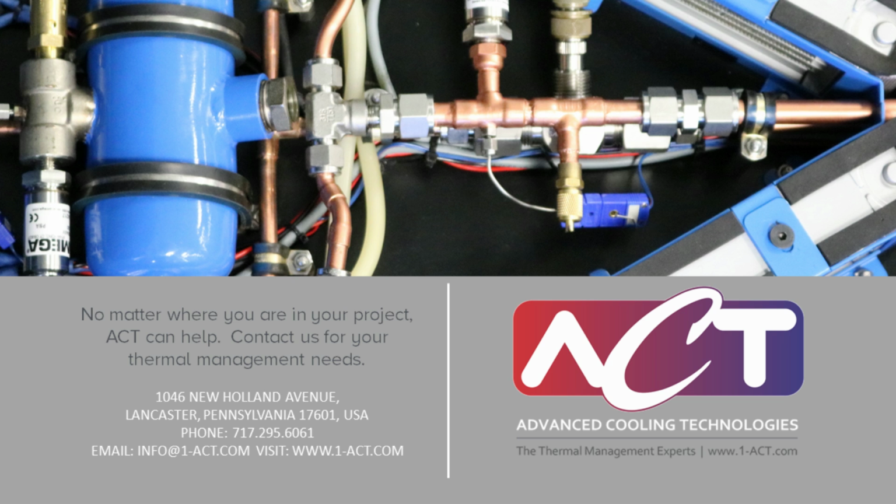to give you something very robust and reliable. So the typical testing might be a couple of thermal performance checks throughout the process, maybe some pressure checks, to make sure that you're able to hold back the vapor pressure of the ammonia as it operates, and maybe a non-condensable gas check where you just burn it in for a short amount of time and see if there's any sort of internal reactions, if it wasn't cleaned well enough, that might generate gas. And those are all typically lot-based.